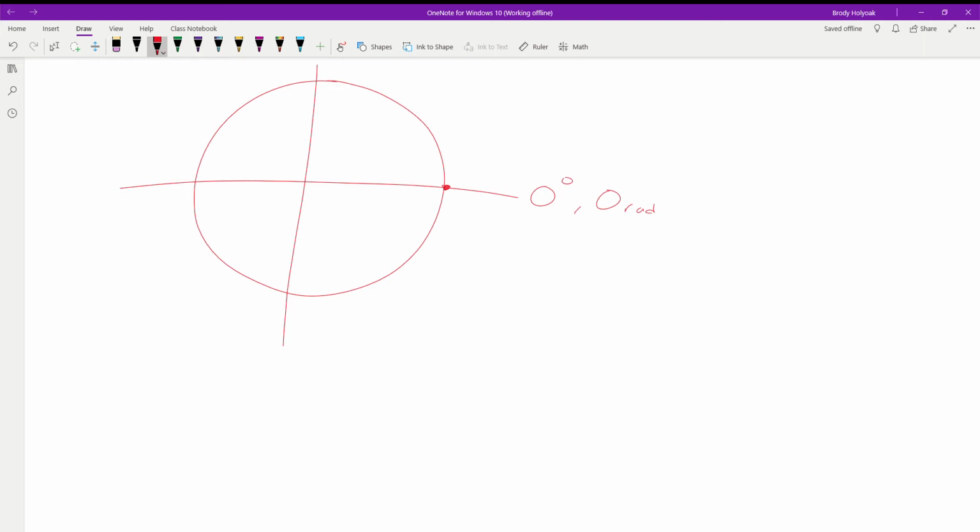The idea behind the circle is this is how motors work. We are spinning something. And in the process, we're spinning a shaft that has either magnets or coils of wire. As we spin these magnets or the coils of wire, depending on what it is, we have other magnets out here, and as we turn them, this is how we generate AC. It's very, very easy to generate AC signals. And so what we're going to reference is the degree of travel, basically. So in a sine wave, if we go all the way around the circle, we have 360 degrees, or 2 pi.